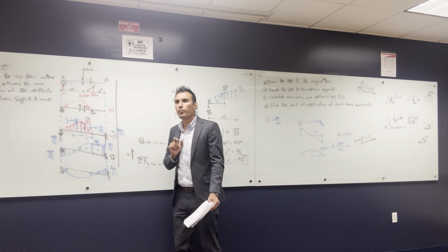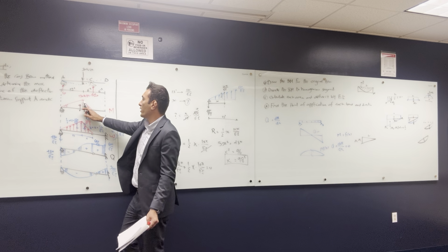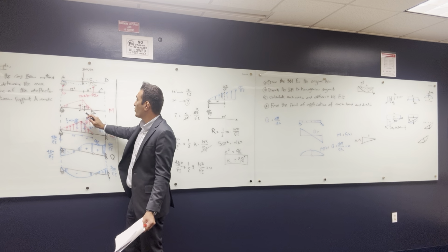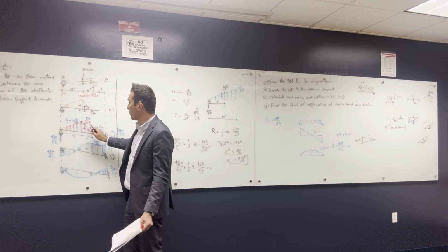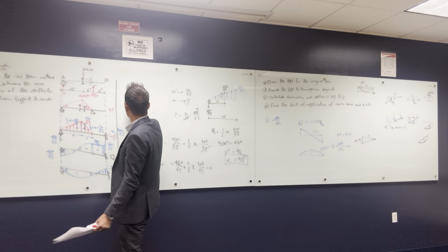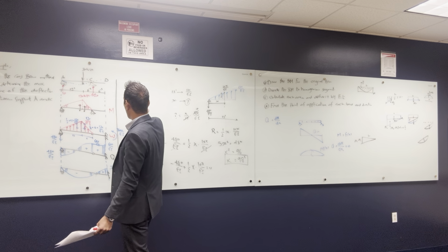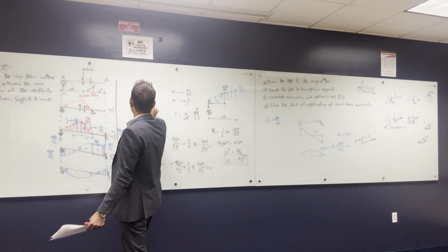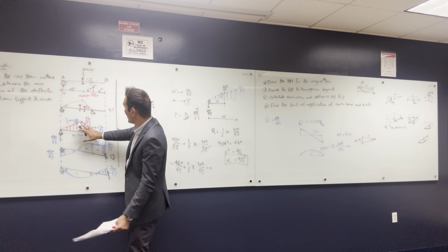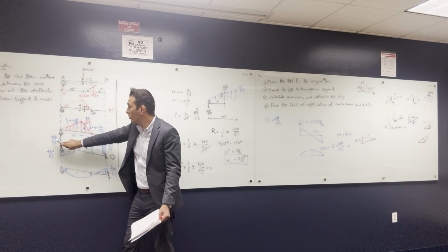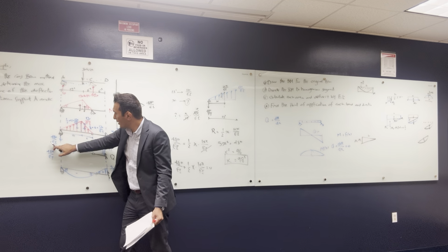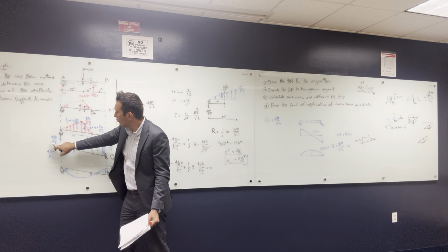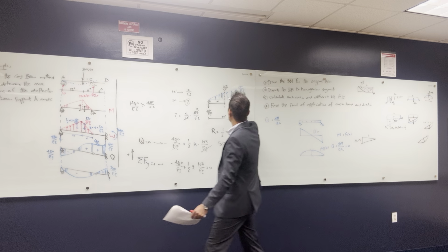And actually, I can know that before I solve the problem. How? Get the area of this triangle. This is 120 and this is 12. You multiply 120 over EI by 12, which is going to give you 1440 over EI, which is bigger than 480 over EI. So this triangle generates loads more than the reaction here, okay? So that means that somewhere, a piece of this triangle can be equal to this value. Maybe the piece that we got, like here, this piece.